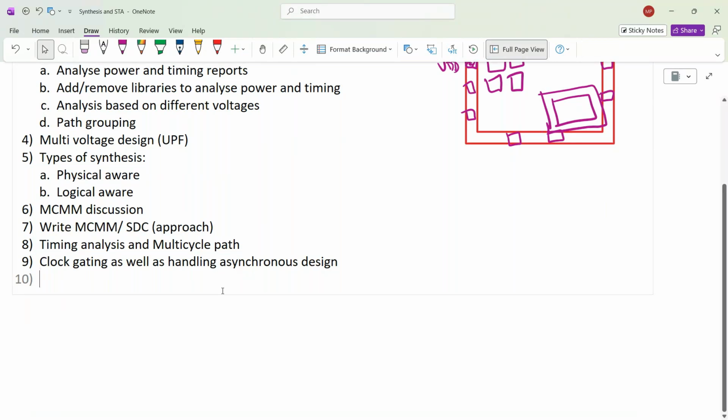If the clocks are asynchronous, synchronizers are required. The RTL team has to add that. We very normally say adding a multi-cycle path or adding a synchronizer in between, but when we are doing that, it does not happen easily. The RTL team has to add that, so all these things have to be done very mindfully. We are going to discuss how to handle it.